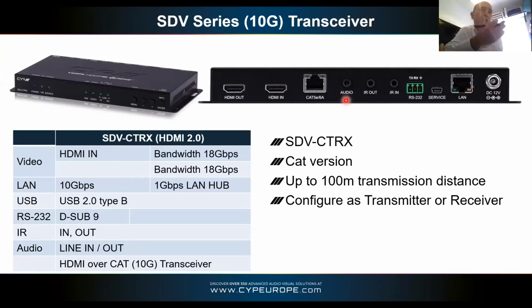As an input, you just use it as standard audio to get the audio across as a separate audio stream. But if you have it as an output, it will de-embed the audio coming in from the HDMI, if in fact that is stereo audio. So you've got dual functionality there. In the receiver, it's just fixed, but in the transmitter, you can decide which way that audio goes.